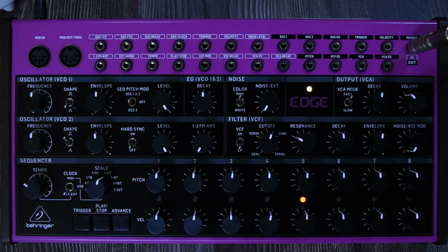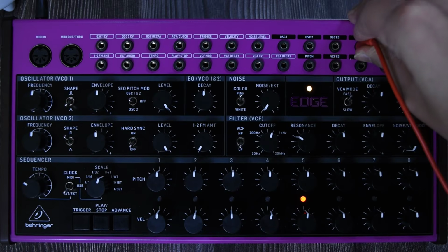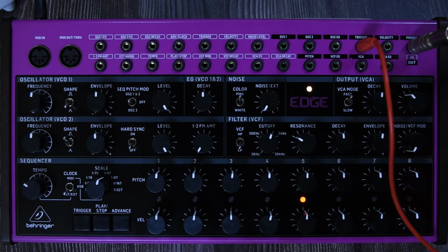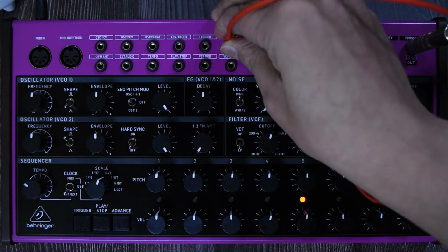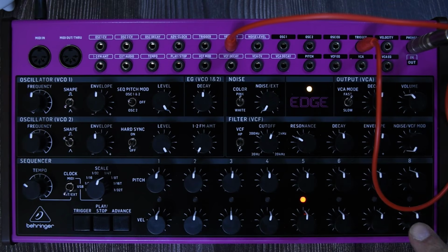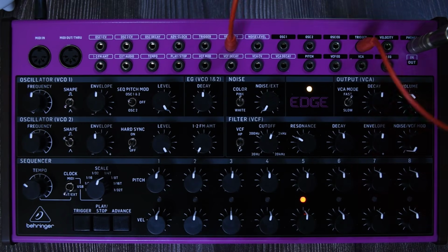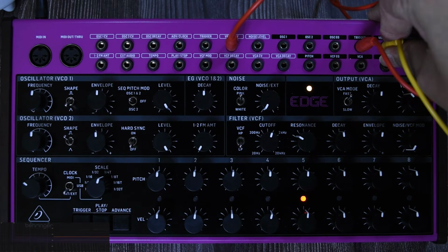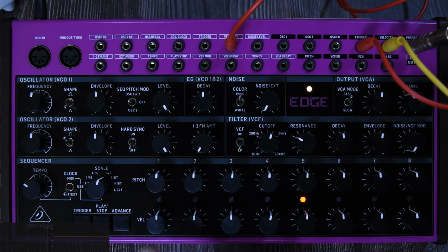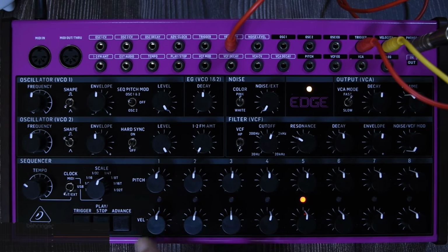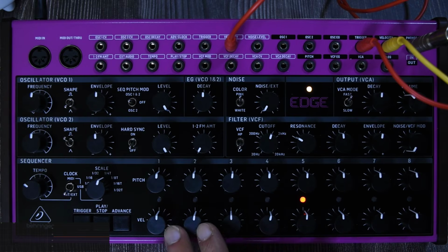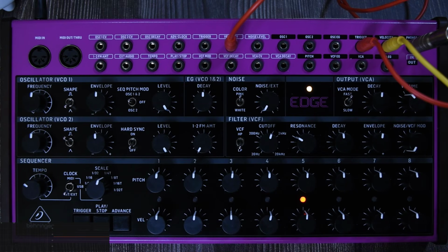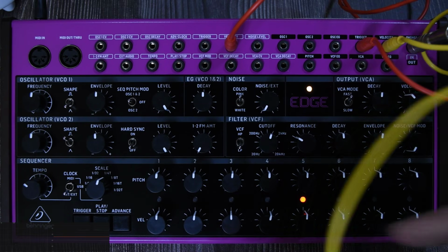And just like this, we could create an example just like we did before. I'm going to connect the trigger out to the in of the velocity, so we can disconnect whatever we do by default with the velocity knobs, and we have them free and we can use them someplace else. So I'm going to be taking the velocity out, and I'm going to be providing an instruction with these controls. And remember, the velocity knobs right here at the bottom do from 0 to plus 5 volts. So this will work. I'm going to take it out.